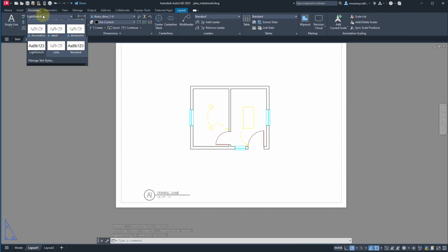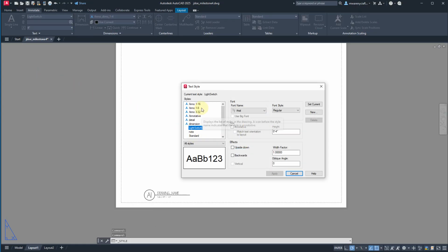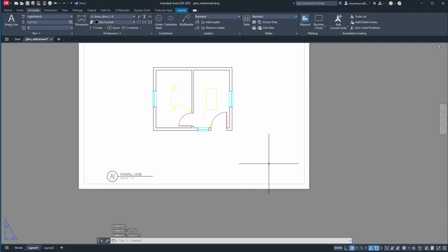Do we need to do another text size? I didn't run this through. Let's just use the 1/4 inch, because that's 1/4 inch right there. So what we'll do is we'll just do a line across here. We'll make this 3 inches across. This is a dirt simple title block. You can always get a little bit fancier with these.